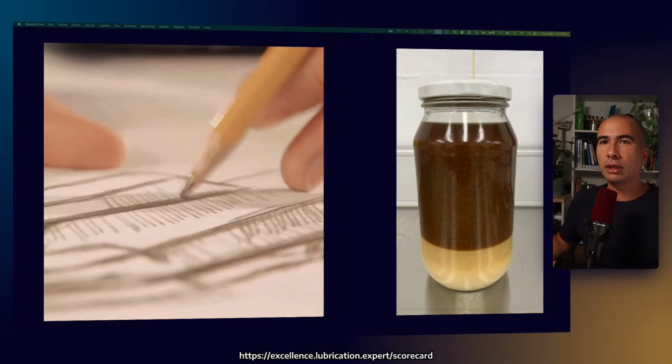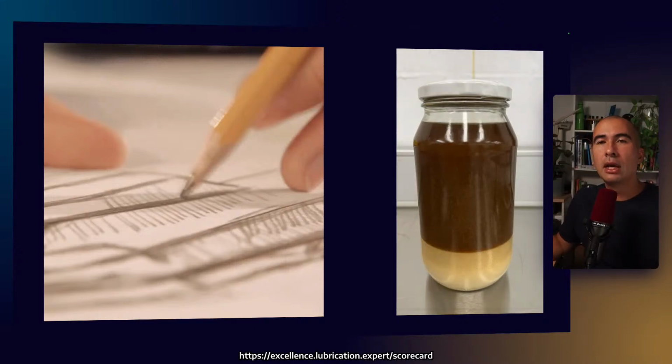So if you wanted something, for example, which is conductive, often you'll use a grease which has some graphite in it, because graphite is conductive, especially in the presence of a little bit of moisture. But in some instances with electrical contacts, we want them to be non-conductive, in which case we would use something with non-conductive solid lubricants. Sorry, that wasn't a perfect answer, but that's not my specialty, I guess.